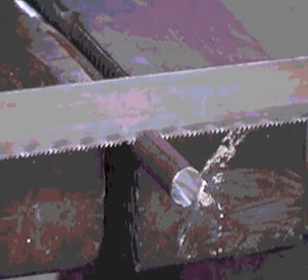The speed of moving the blade should be around 40 to 50 strokes per minute. You should concentrate on the saw while moving it and move it exactly in the same vertical direction. There should not be any distraction. You should concentrate on the saw so that it doesn't get tilted.